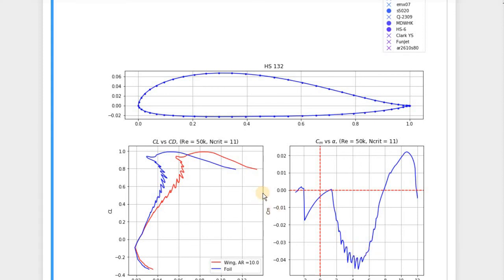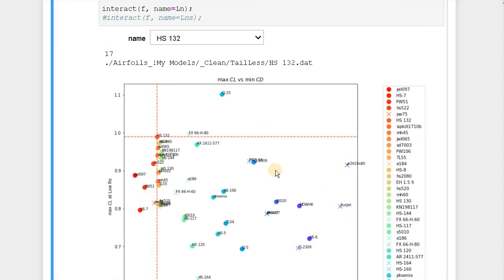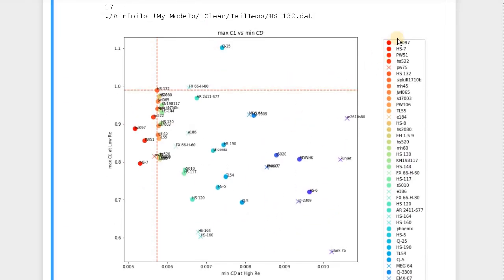And I think that's it. And probably we are ready for picking the best airfoil. Those airfoils are already sorted, so those having the smallest drag coefficient, for instance, PW51, is number 3 in this list. The only thing that you have to look at is to have the maximum lift coefficient that you need, because this will define the slowest speed you can fly. But I think that all airfoils with this small drag coefficient are good. They have sufficient lift coefficient, so you can pick any of those.